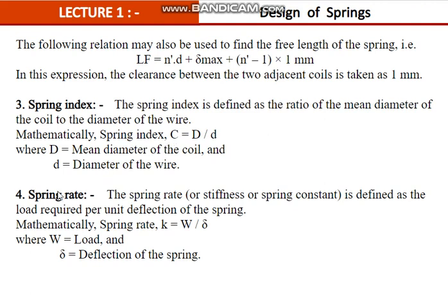And then spring rate. The spring rate is defined as the load required per unit deflection of the spring. That means, if you want to press it by 1 mm, how much load is needed? How many newtons are needed to press it by 1 mm?